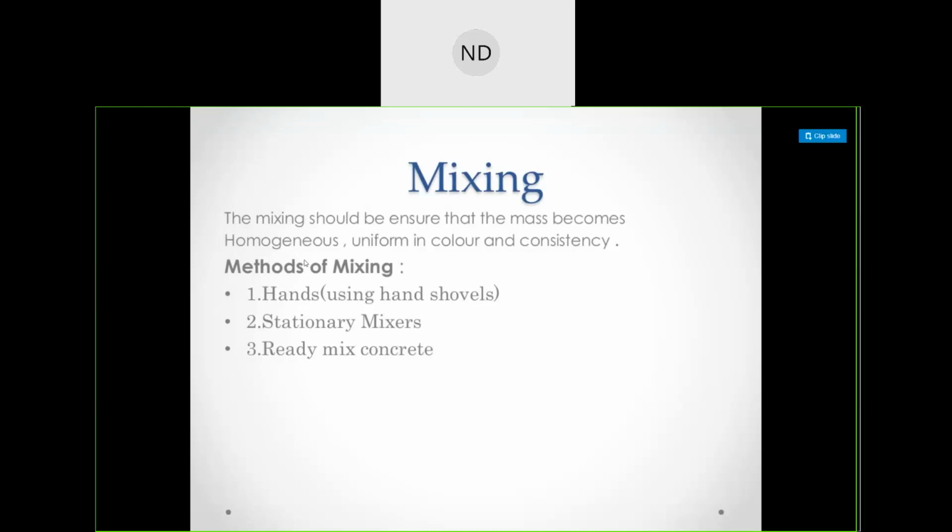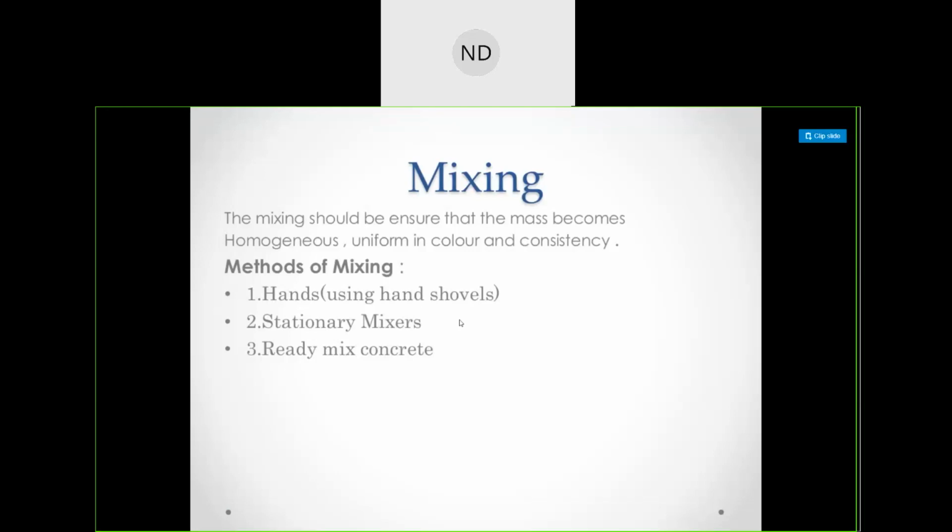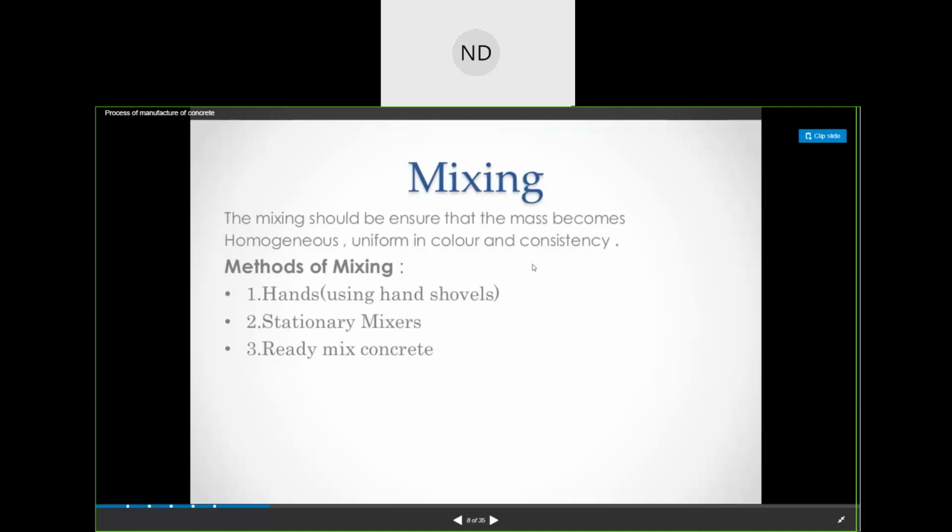Then what you will do, you will place them. After transporting to the site, you are going to place them, then you are going to compact, right? Obviously you cannot give 100% compaction, you cannot see the air present in your concrete mix. You will try to give compaction because you want to remove those 6% air also, but somewhere or the other you will have at least 1% air inside, as compared to your mix proportion, or how much quantity you are using.